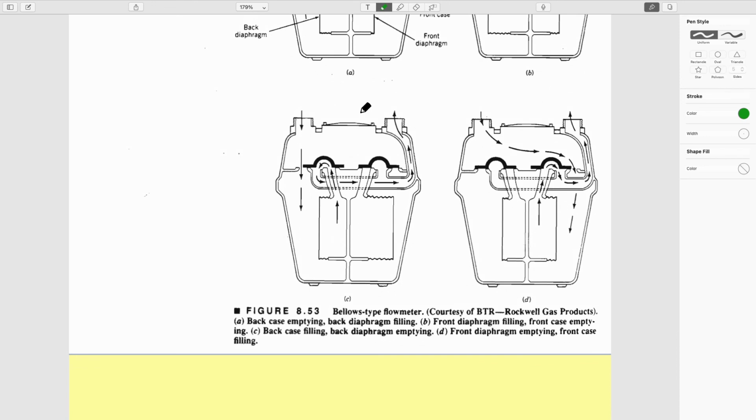And so three methods. Either measure pressures by constricting flow, and that gives you a flow rate. Balance of momentum, either with an impeller or with a bead, like in a tire. A tire gauge works on the same principle. Or by measuring flow volumes into a volume. So I don't think you have it now, but it used to be when you bought gas, there used to be a little four-leafed thing that used to spin within the flow. You used to be able to see it as it metered into your car. And same principle as this. A given volume in something you twist around.